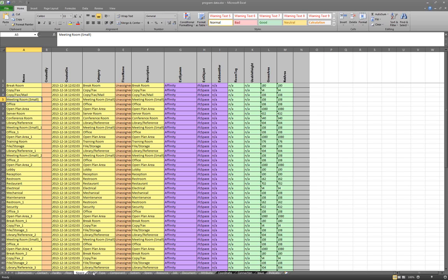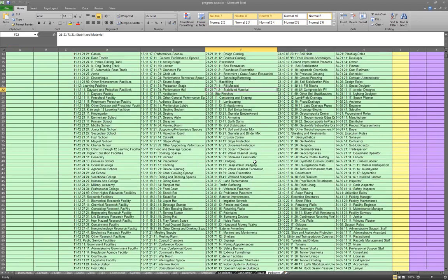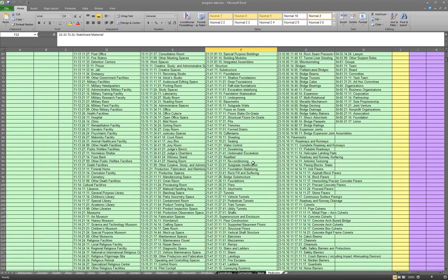It's also used to input information into a facilities management tool. So you can export out to the COBie format and import this into your facilities management tool. It has all the information that you would need to put into that application. Right? So you have your rooms, your objects, your departments, and even supplemental information at the very end that you would need in that FM tool.